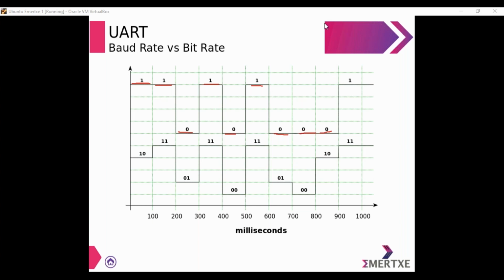I would maybe write it here. So first of all, bit rate, I'll write it as bi, is nothing but n multiplied by baud rate. Here baud rate is number of symbols per second. In the first scenario I have 10 symbols per second, so it is 10 multiplied by 1, since each symbol is made up of only one bit, so it is 10. So bit rate in the first scenario is the same as the baud rate because each symbol is made up of a single bit.